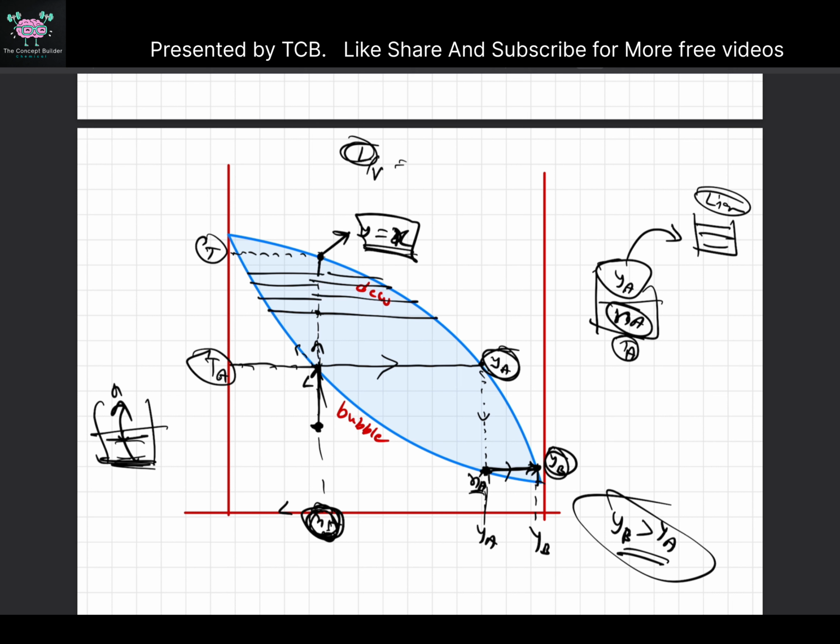This also tells you another thing: if you don't have liquid and vapor contact, if it's 100% vapor, there is no distillation, because there is no enrichment, because y equals x at this point. We want y greater than x for our distillation, correct? So this is another point.